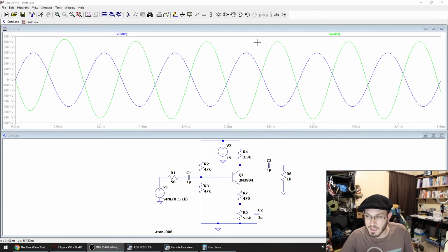Okay. So what I'm doing is I'm illustrating how we are really at the mercy of our impedances at the end of the day. So it doesn't matter how accurate of an amplifier you design. If it isn't low impedance compared to the load that you're trying to drive, you're going to always end up losing your signal.